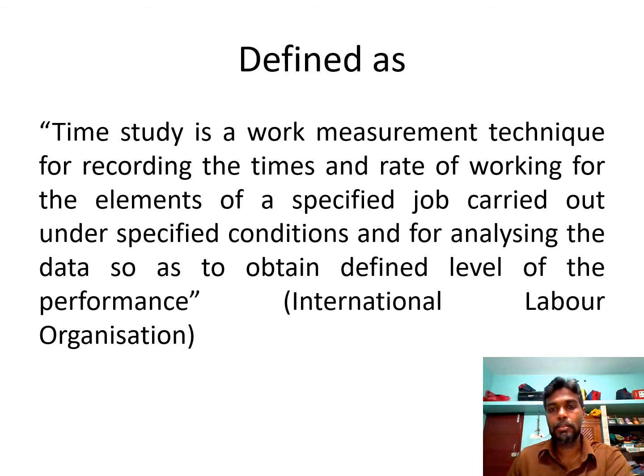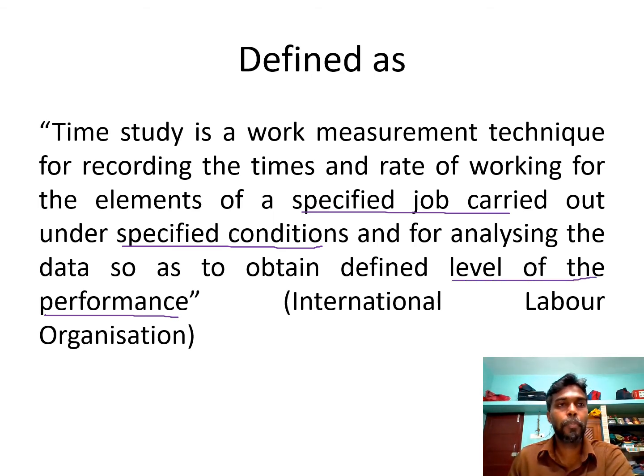As per ILO, that is the International Labour Organization, time study is defined as a work measurement technique for recording the times and rate of working for the elements of a specified job carried out under specified conditions, and for analyzing the data so as to obtain a defined level of performance. So finally they are evaluating the defined level of performance, whether they achieve the performance based upon the given specified condition and specified job. You are continuously trying to train and continuously updating, and again you are checking whether you achieve the performance or not.